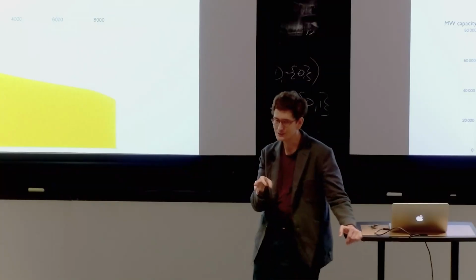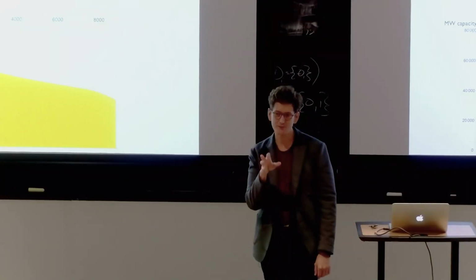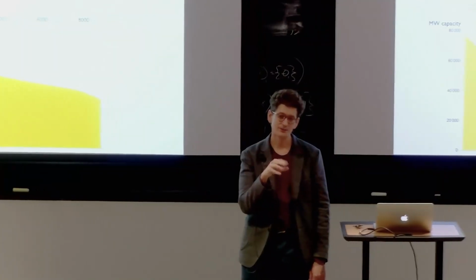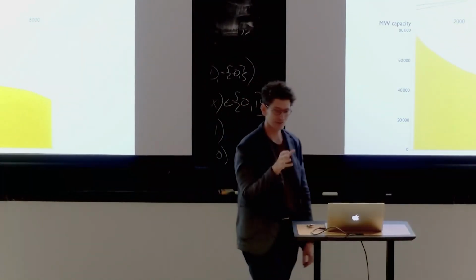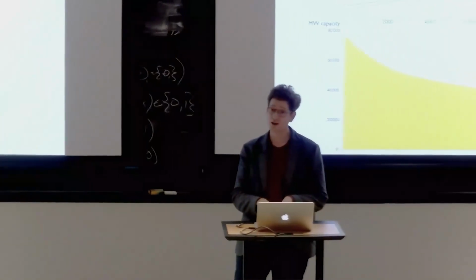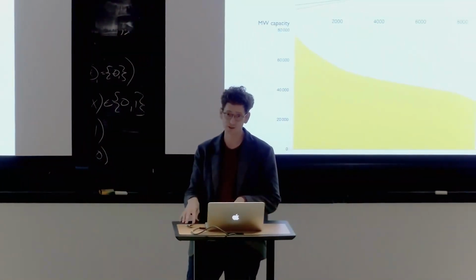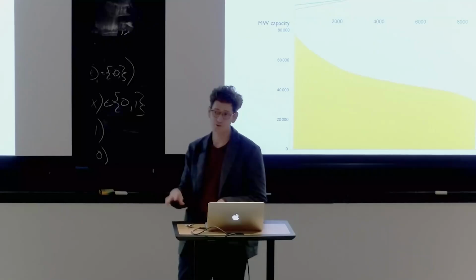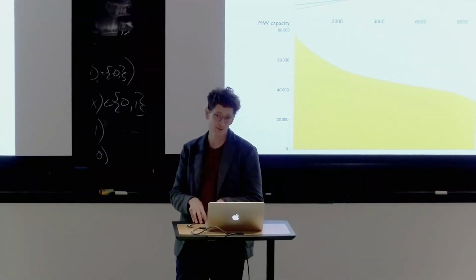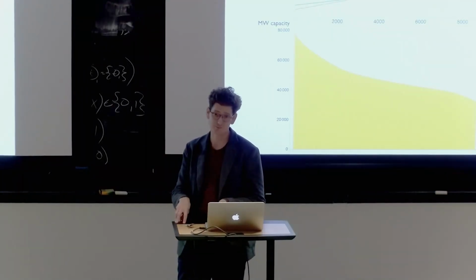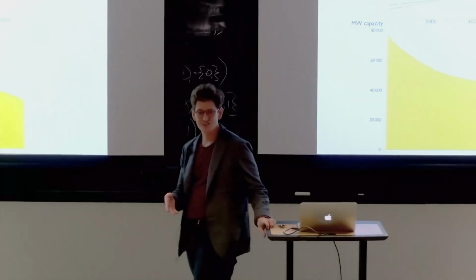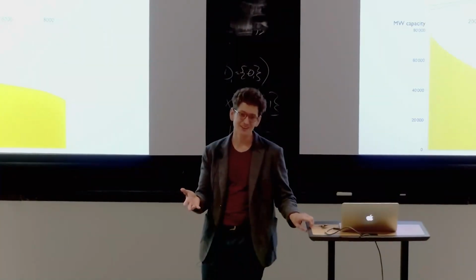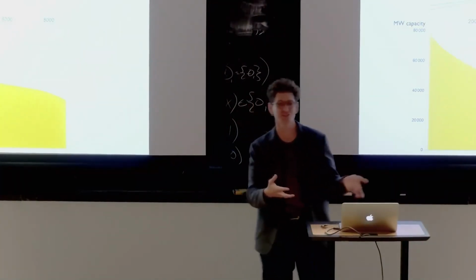So volatility is an issue if the generators can't respond to volatility. So that's absolutely correct that for traditional thermal generators, a highly volatile market is problematic. For inverter-based generators, a highly volatile market is not problematic because they can instantaneously curtail within a millisecond. So people who are thermal generators or inertial generators complain about volatility, and those who are not inertial generators do not.